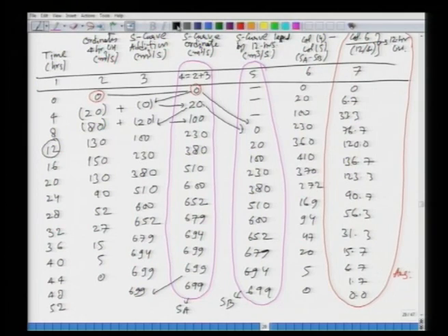All right. So, what we have done today is we have looked at two methods of determining the unit hydrograph of different duration. Given a d hour UH, we are finding n times d hour unit hydrograph, where n was an integer in the first case. All right. We use what is called the method of superposition. And if the n is not an integer or it is a fraction, then we can use the S curve, and we have seen a very compact method of how to find the S curve, and then how we can use this S curve technique by lagging and by using the principle of proportionality and superposition to find out the unit hydrograph of a different duration.